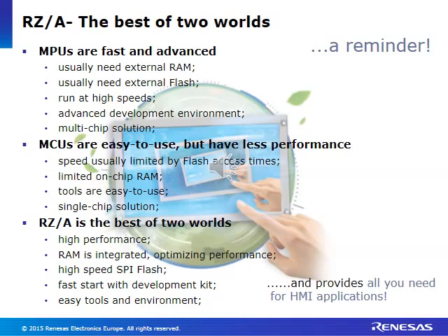For many people, the distinction between microcontrollers and microprocessors is just about integrated flash memory, where microcontrollers have embedded flash and MPUs don't. However, microprocessors and microcontrollers actually differ in more aspects. Microcontrollers have very high digital and analog peripheral integration, as well as high-density embedded RAM and flash, which belong to the most important parameters of scalability next to performance.